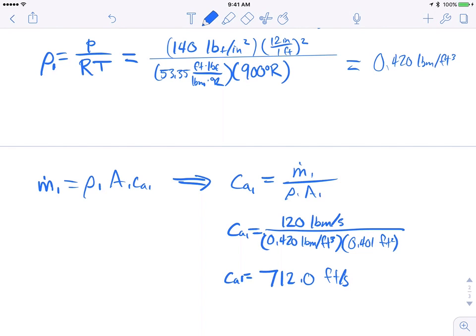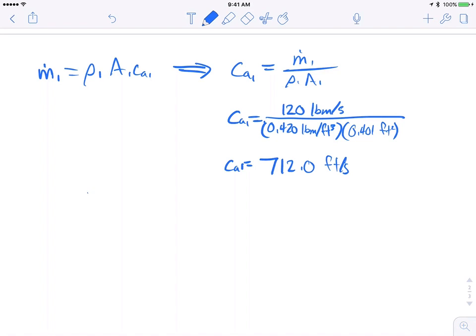So now we know the axial flow velocity, and that's at least one leg of our absolute flow vector coming in. If that's C1, we've got our 18 degrees. We know CA1. Now if we can calculate CU1, we can also figure out our absolute velocity. The magnitude of our velocity vector C1, since we're dealing with a right triangle, is going to be C1A over the cosine of alpha, our absolute flow angle.